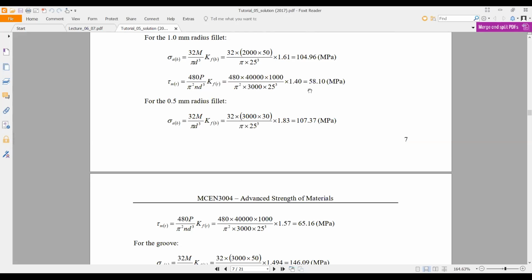I told you, if the curves cross, the minimum point and maximum point are on two different lines. At 10 to the power 3 cycles, the minimum value will be provided by one SN curve, and you need to consider that curve. If a different curve provides the minimum strength at 10 to the power 6 cycles, you need to consider both curves, find the values for both, and check which one has the minimum value. I told you this last time when we discussed the tutorial.